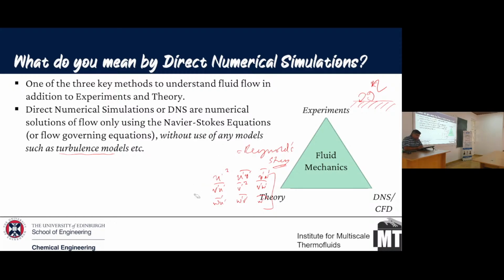Okay, people use K-epsilon models for boiling, condensation, and we do compare it with experiment. If it falls within 30% of the error, we feel very happy about it. Okay, so they're not the best models, but they're there.